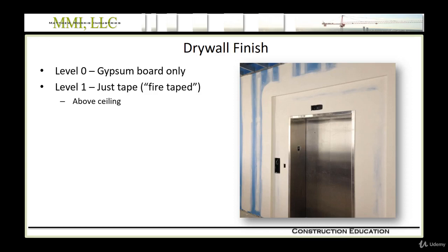But for most commercial jobs, a tape tool is used and it's called a banjo. It looks like a big tape dispenser like you use when you're using packaging tape. It has a roll of drywall tape inside and also joint compound inside. And when it's rolled out, mud is already applied to the back of the tape. This saves a lot of time.